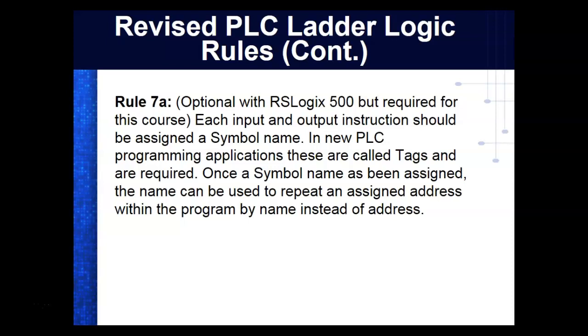Each input and output instruction should be assigned a symbol. Or if they've changed the name, now they call these tags. So if you get into RSLogix 500 or the TIA Portal, they're going to talk a lot about tags. In new PLC programming applications, these are called tags and are required. Once a symbol name has been assigned, the name can be used to repeat an assigned address within the program by name instead of address.